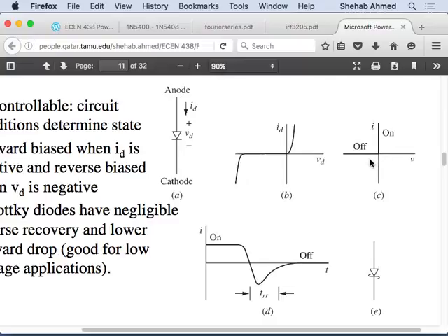So in power electronics, a lot of the time we consider the switches as ideal during the initial stages of the design. And then, of course, we cannot consider them ideal forever. We then have to consider the power losses. So that's why we will draw an IV characteristic that looks like this. Instead of this exponential that has some voltage drop when there's current, meaning there's power loss, forget about that. I don't care. When the voltage is positive, the device is conducting.